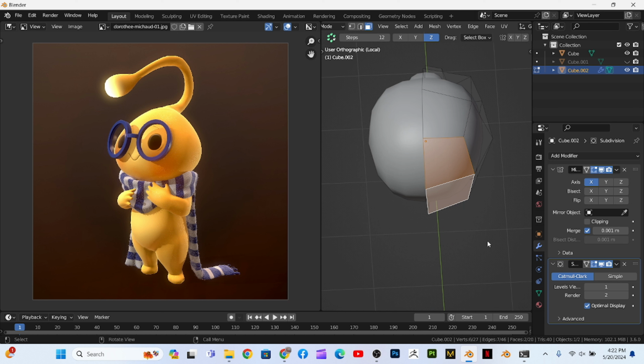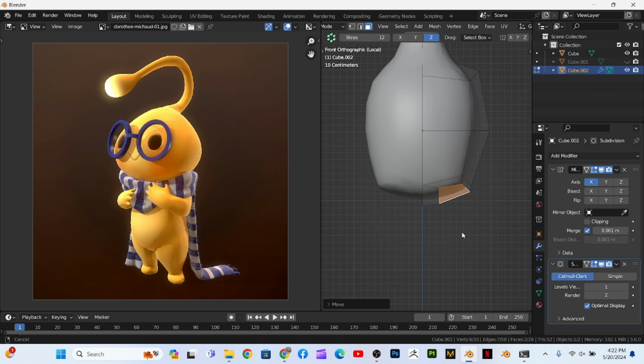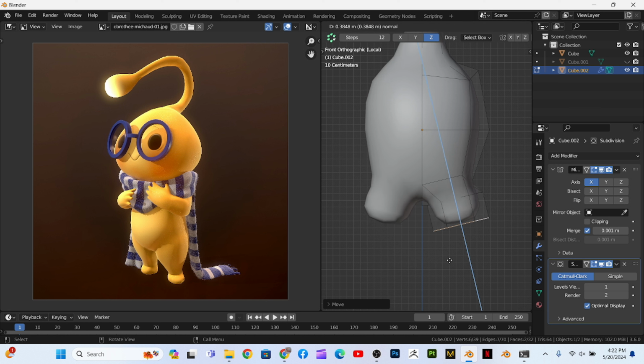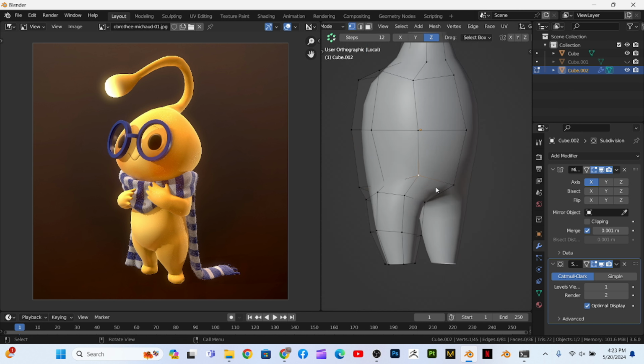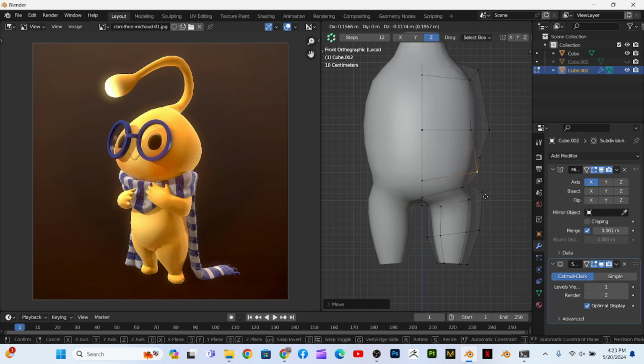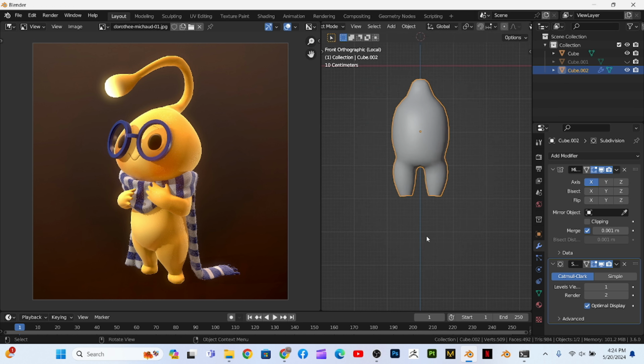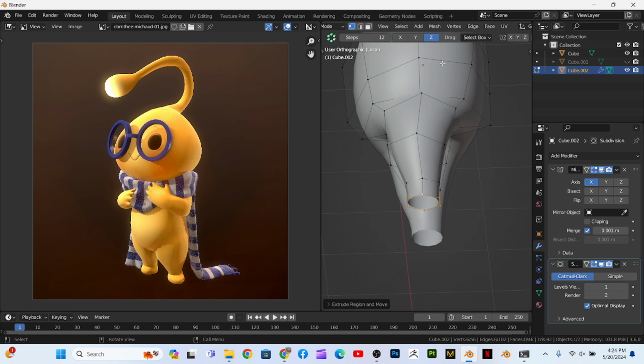Select these 2 bottom vertices and press I and B to insert faces with a bridge. Make the selection circle using loop tools, move it out and extrude it out to make the leg part. Delete the bottom faces, adjust these vertices to make the body shape right, make the adjustment until it looks right to you. I added a loop cut tool, select the bottom edge face and fill these faces.